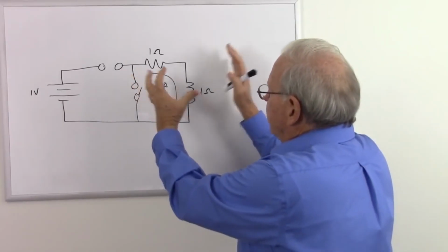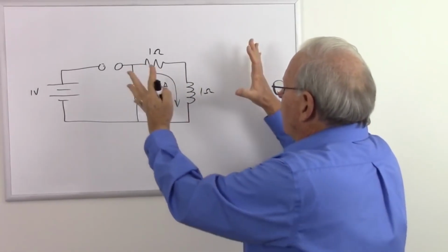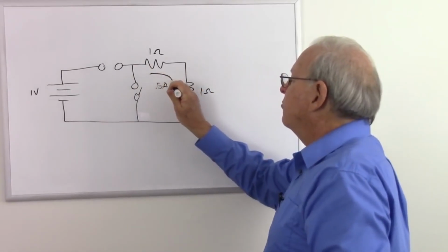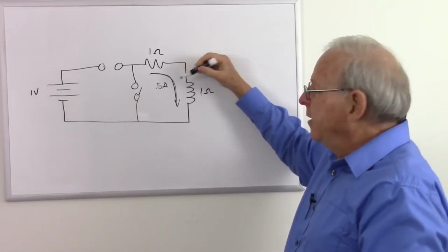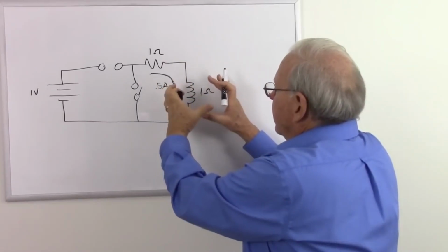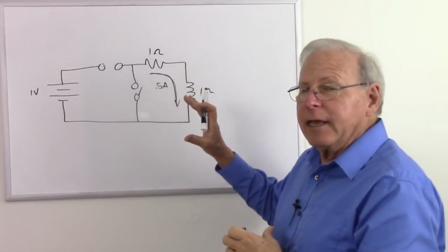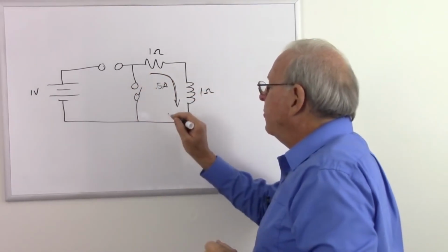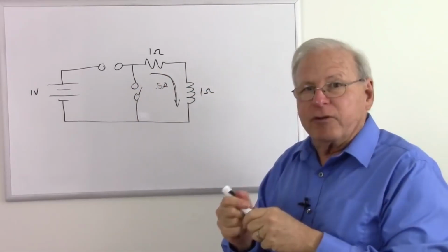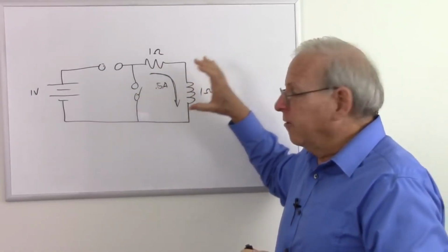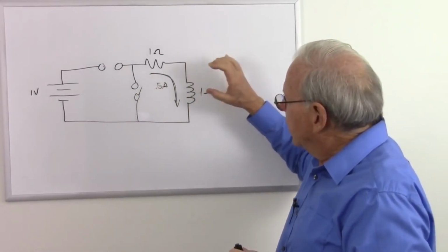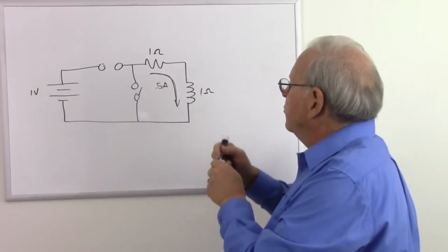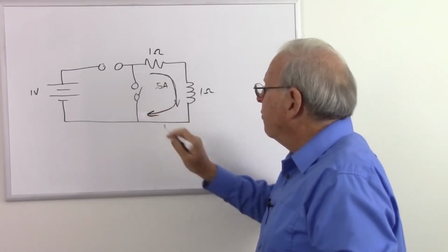So that magnetic field is collapsing, it's getting weaker, and so what's going to happen now, as it's collapsing, it's going to generate a current in the same direction. So when we pushed current in, it built a magnetic field which generated a current which pushed back. Now, as that magnetic field collapses, it's pushing in the same direction. So at first, we try to put current into it. It says, no, I'm an open circuit. But after a while, it looked like a short circuit, except for the resistance in the inductor. Now it is pushing current in the same direction.